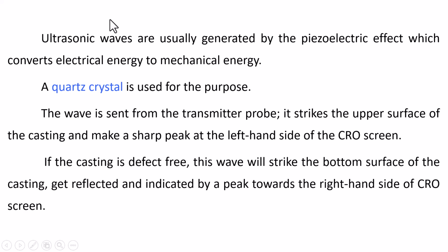Ultrasonic waves are usually generated by the piezoelectric effect, which converts electrical energy into mechanical energy. So using a piezoelectric crystal, the electrical energy is converted into mechanical energy. It produces vibration, and those waves pass through the material. A quartz crystal is used for this purpose.